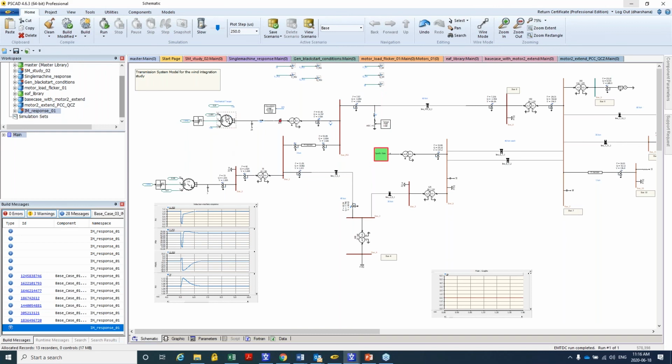the rotor winding is not just shorted, it is connected to a supply or to the grid through a power electronic, back-to-back inverter setup. So by controlling the power electronic inverters, you can actually inject currents into the rotor winding and avoid this from happening. You can actually control the reactive power, right, of the type 3 or DFIG following a fault clearance. So type 3 became popular for that reason.